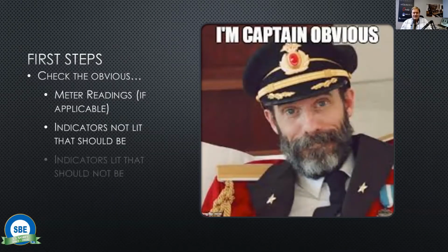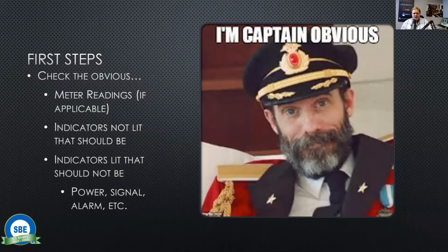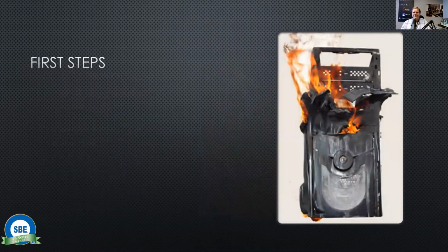Did it lose its source of power? Any indicators lit that should not be? Oh, what's this big red alarm light on this piece of equipment? Okay, is it that piece of equipment, or is it something upstream from it? Look for power, signal, alarm lights, all that fun stuff. So our first steps.